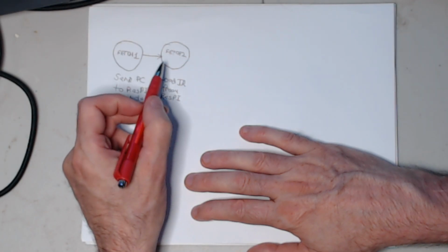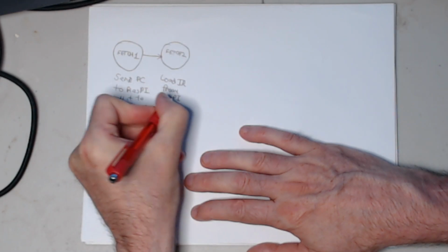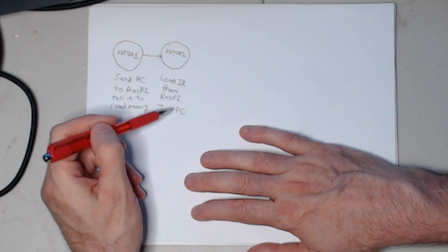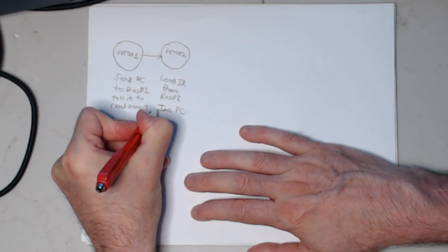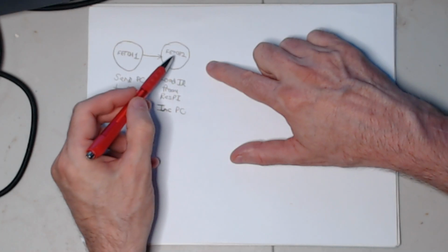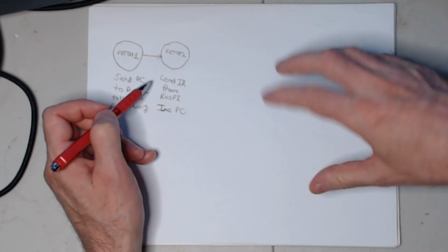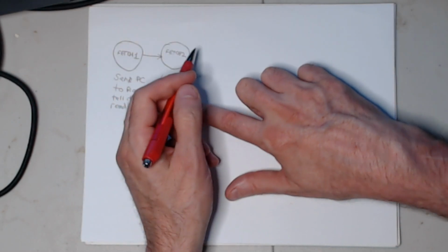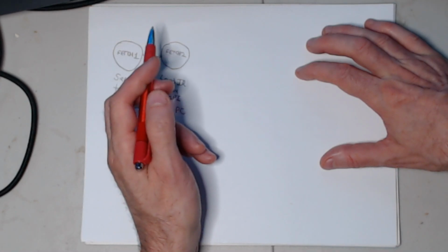Now another thing the fetch 2 cycle is going to do is increment the program counter. Okay, so that's sort of a separate thing. So it's doing two separate things here. It's going to increment the program counter. So that's sort of what the fetch 2 state does. It's going to load the instruction register from the data it gets back from the Raspberry Pi and increment the program counter.